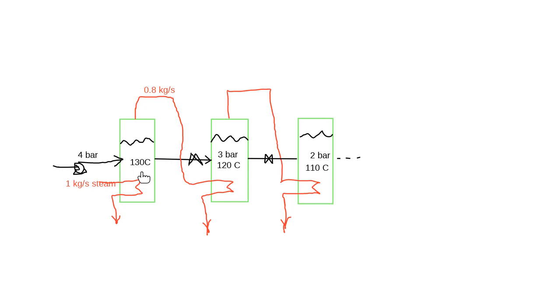There's not much difficulty about it, except that you need to go to higher pressures. And we'll also talk about what happens with that rise in boiling point. As you get a higher rise in boiling point, it becomes less effective, or you can't have as many things in series before you run out of pressure, and therefore you can't have as many effects.